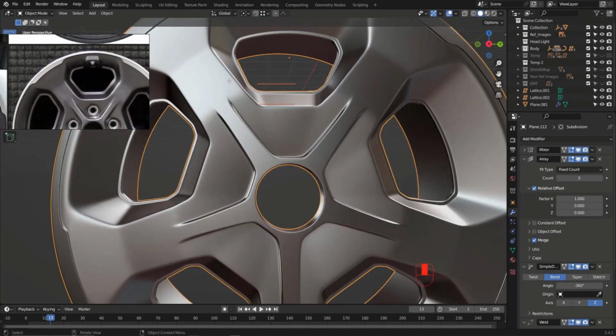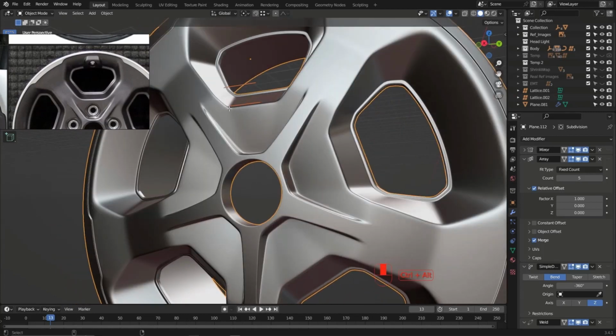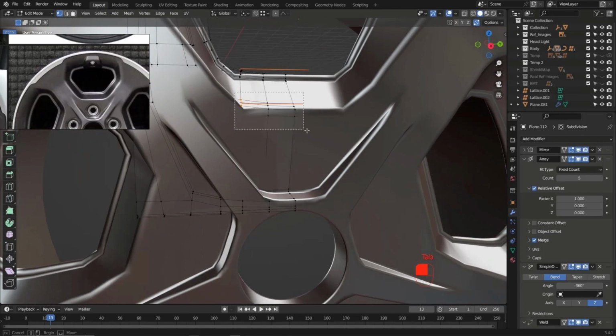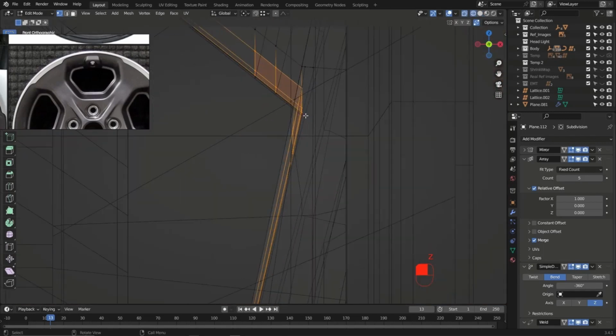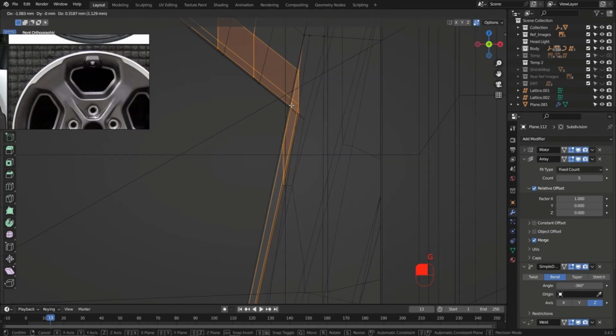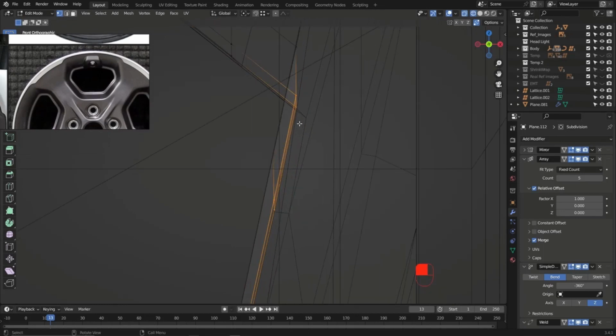Because we moved these vertices down, we lost this flat face we have right here, and we need to fix it. The same thing, we could go to the front view and go to wireframe, and let's see what we have done here. Just take these edges back one by one, grab those over here and hit G, and